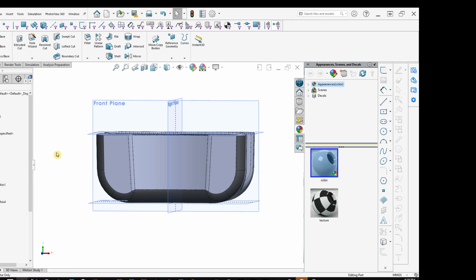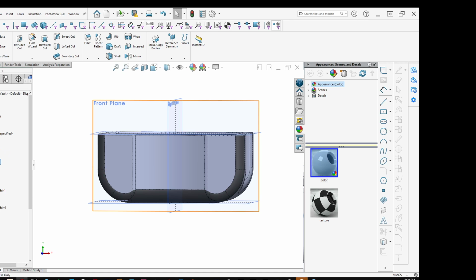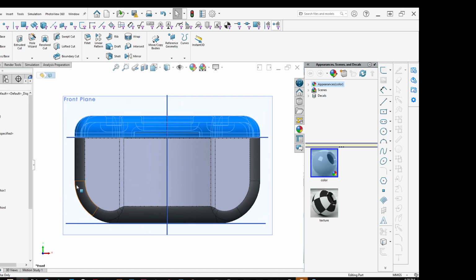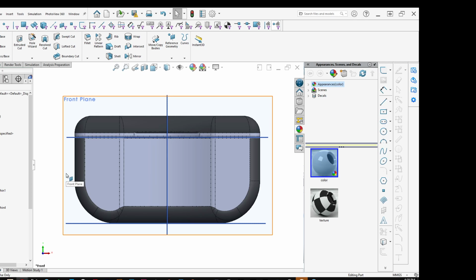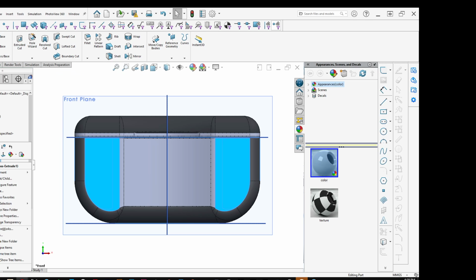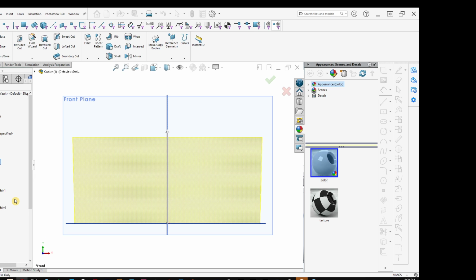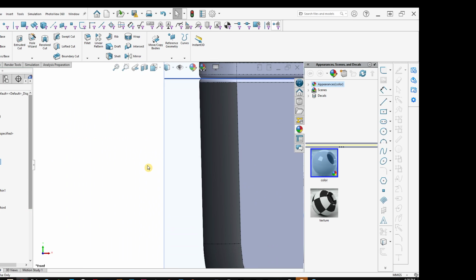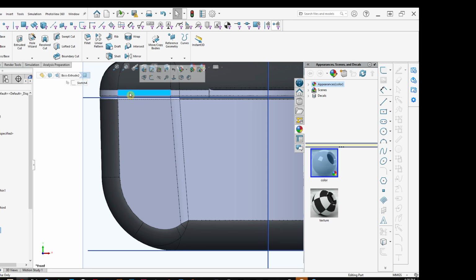Now, here's where I'm talking about, where before, and let me just go back, and we will turn off draft here. So you can kind of see here, you've got that perfect straight line there where it goes up and it mates beautifully. So if we now come in and we go, okay, well, we need to put 1 degree, or we're going to say 1.5. 1.5 degree here. It starts affecting the look. Did that go in? Okay, so not very noticeable. Doesn't look bad. But let me just see if I can find where that is. Okay.